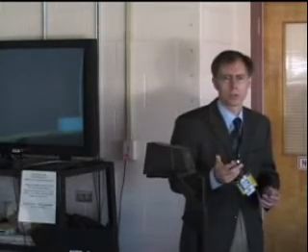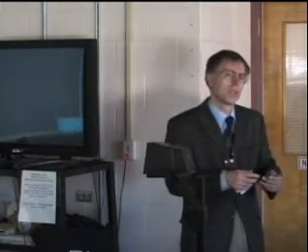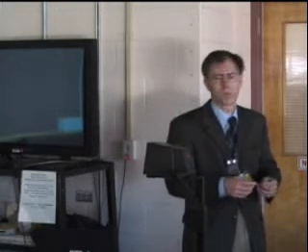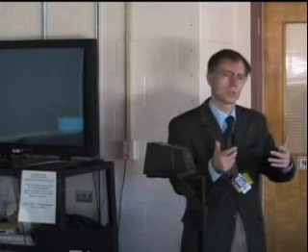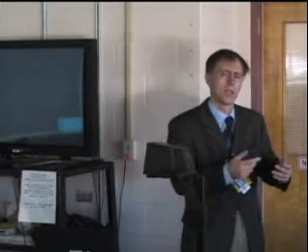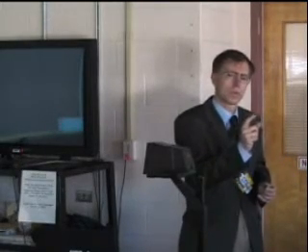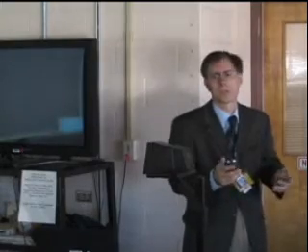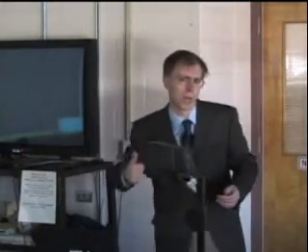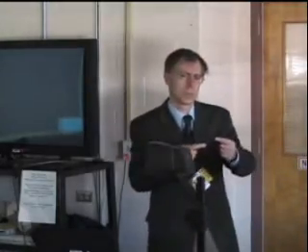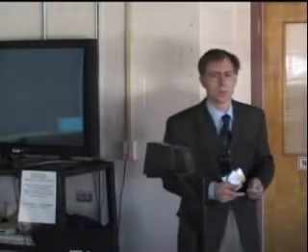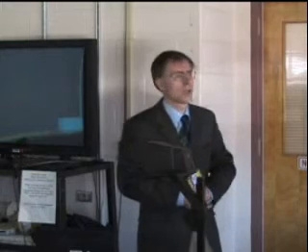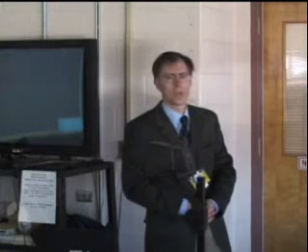You want to do all 200 measurements, and you want to change a couple of parameters to see where the numbers go real quickly. So what we do is we have a mechanism to export enough information about each measurement to a comma delimited file that you can pull into Excel, edit it with the changes that you want for, like declared mass or maybe efficiency or whatever the fields are, and then you can run that file back through. It will find the measurement, do a reanalysis of the measurement with the changed parameters, store it in the database, and optionally generate a report. So yes, we have that working now. And that is going to be a part of INCC in the near future. I don't know when yet.